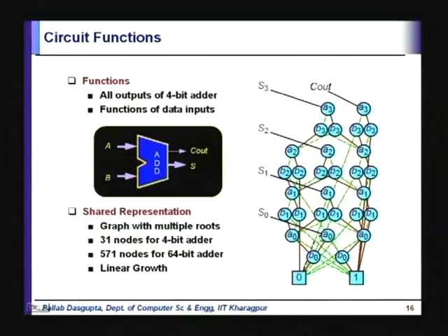If you have a multi output function, then you put them all on the same BDD so that they can share as many of the sub functions as possible, right. So, for example, see, this node represents S0, but that is being used by the BDD for S1, and the BDD for S1 is being used by the BDD for carry out. In fact, carry out is going to use all of these, I think, right. So, that is the thing.